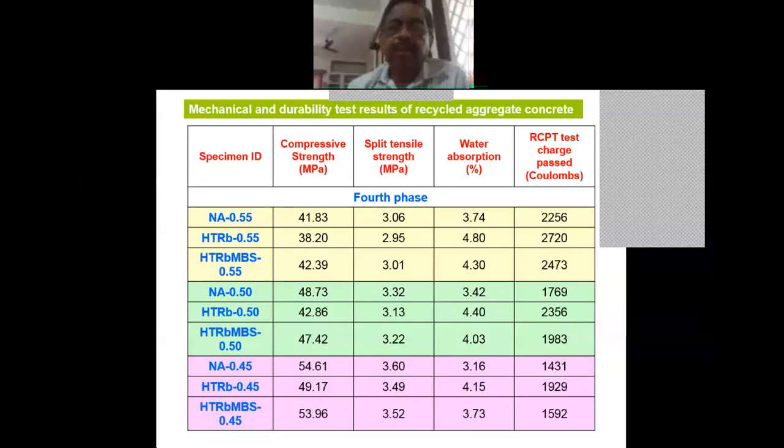The materials you are using have to be adapted properly in the mix design, and then you can try it. Definitely we know that when the water cement ratio is high, the durability values will be lower. So the reduction at 0.45 may not be due only to microsilica; it is due to the reduction in the water cement ratio and cementitious ratio also. So that way we can take the things.